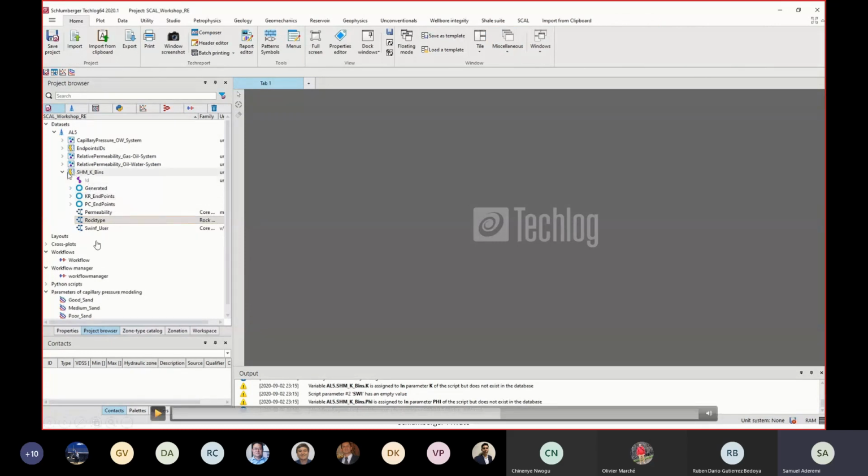Remember now that we have generated the relative permeability. That is what is inside the generated folder. We just want to generate the capillary pressure. But for us to generate the capillary pressure from the saturation height module, we have to have at least the dummy capillary pressure and the dummy saturation corresponding to that. Since we brought in this data without making provision for that, I can just grab the capillary pressure from the previous data sets from the lab and just put it here.